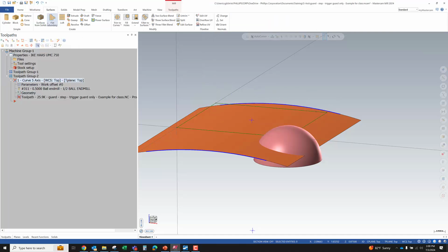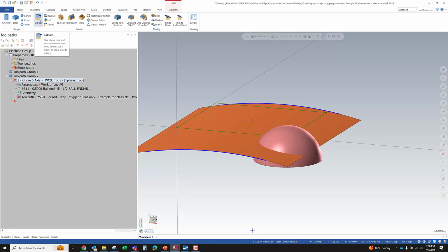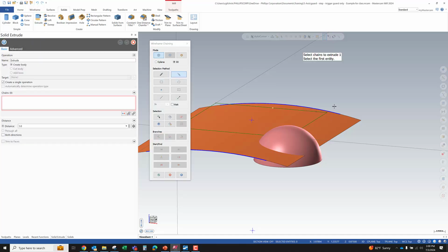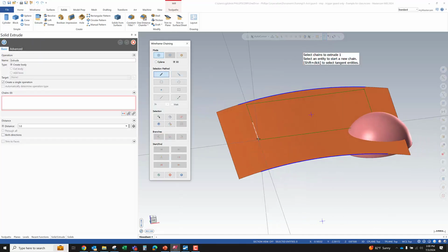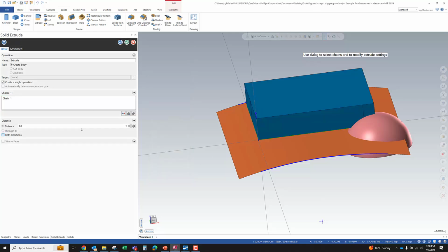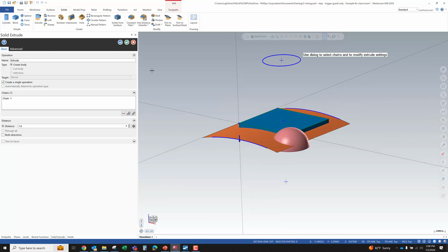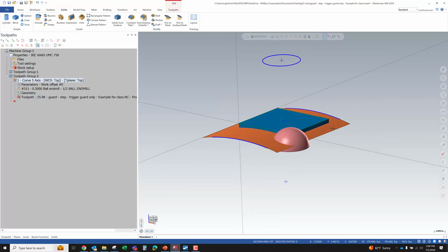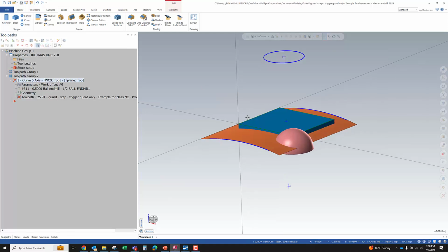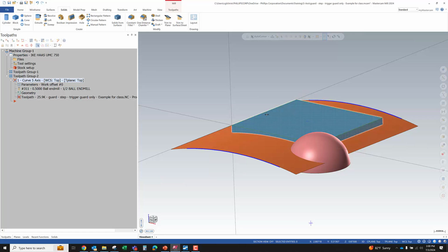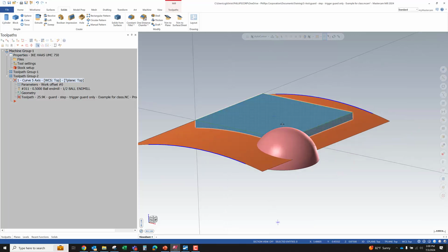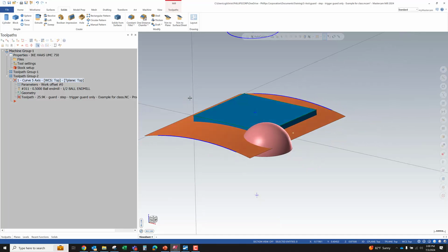What I'm talking about is a solid, right? So I'm going to do solids, extrude. Sure, we're in full chain mode. There's my chain. I'm going to reverse it. Sweet. I got solid geometry. I want to cut around the edge of that thing, and I want to do it on the face here, and maybe I'm trying to break the edge, whatever I'm trying to do. I want to cut it in a certain way.